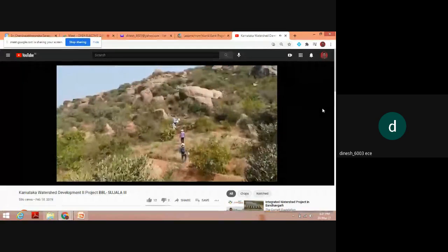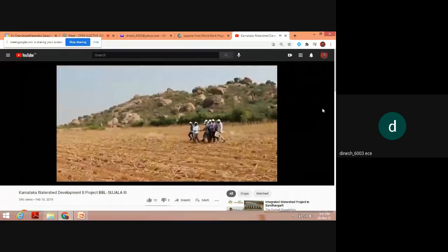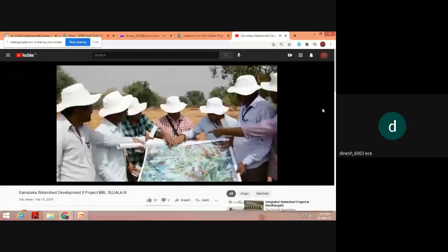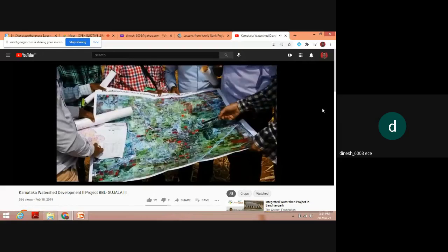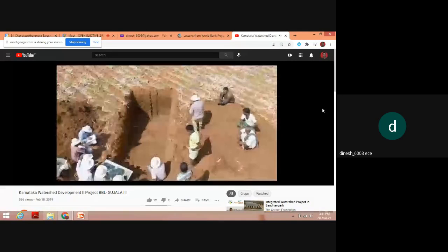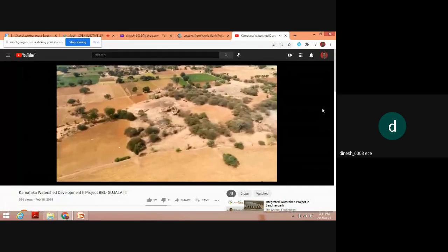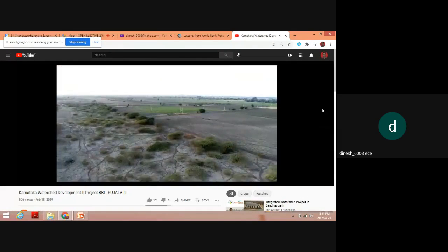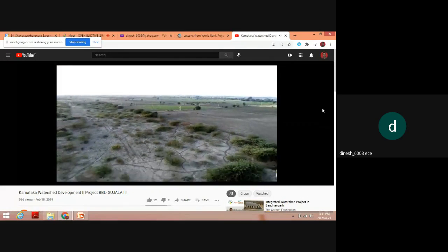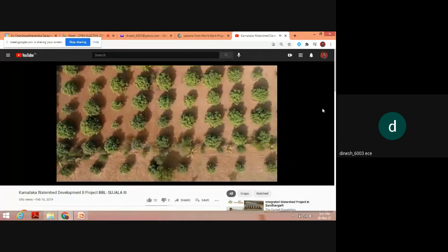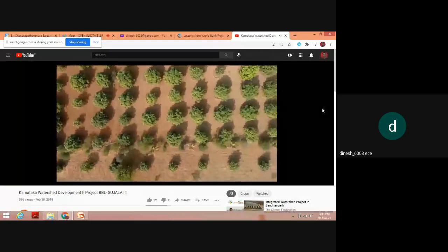The watershed area is traversed by the LRI team to verify the landform units, select locations for transects from ridge to valley, and representative fields for profile study. During traverse, any change in slope, erosion, drainage, soil texture, salinity, cropping pattern, and land use details are identified and indicated on the map.